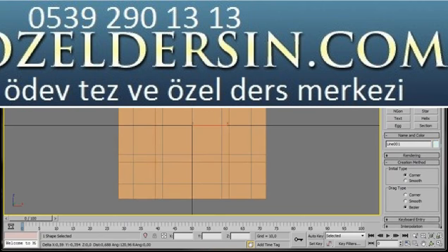I'm just going to click once to drop the first vertex. I'll hold the mouse down and drag it as I click a few more times. Notice I'm getting a weird shape. These are Bezier vertices. If I just move the cursor without holding the mouse down, I'll get straight lines. If you want to delete the last vertex, just press backspace on the keyboard. Okay, all I have to do now is right click to come out of the line creator mode and delete it. For this video, I'm going to change my drag type to corner.